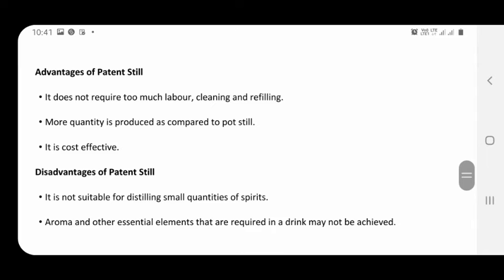It gets heated up by the hot vapor rising up the column, and the vapor cools when it contacts the cold wash pipelines. The hot wash enters the analyzer column at the top and flows down over a series of perforated plates, meeting the ascending steam, and the alcohol vapor rises. The balance of the wash, which is heavy in impurities, is drawn off at the bottom and converted into animal feed.